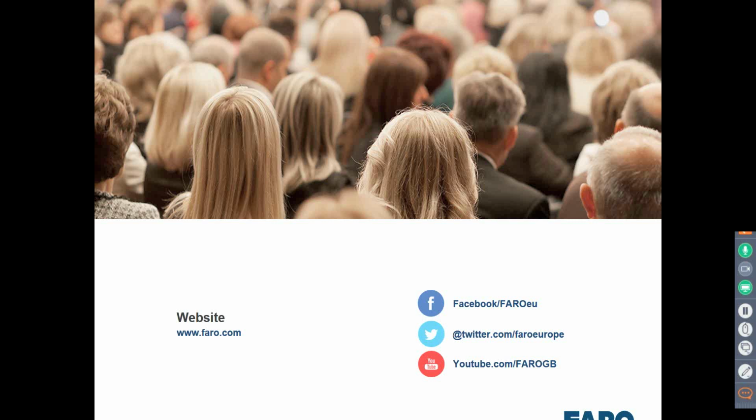I think very distinct aspects where this would come into play are drilled holes. I'll use that as an example. Are they there? Absence, presence. Are they in the wrong location? We see that a lot. Are there cutouts? And those cutouts are either absent, present, or in the wrong location. And Visual Inspect, the AR feature, will very quickly let you see that and document that. So hopefully that answered the question.